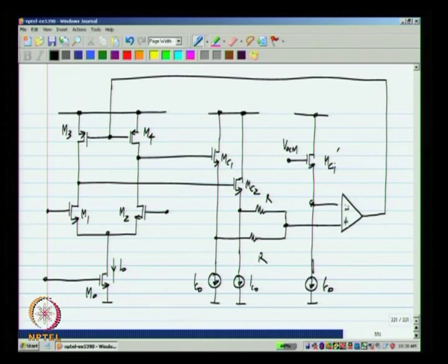We will see how to make this particular op amp shortly. Okay. So, right now this is what the circuit is. And you can also see that in the differential picture, this point will be at ground and these two will in the ideal case offer no loading. In reality, because of CGS of MC1 and MC2, there is some small loading on the single stage op amp. Okay. I have not shown the integrating capacitors of the single stage op amp.